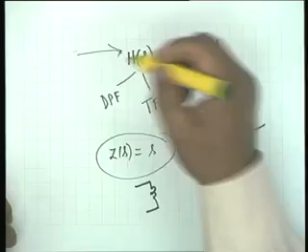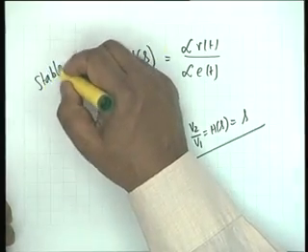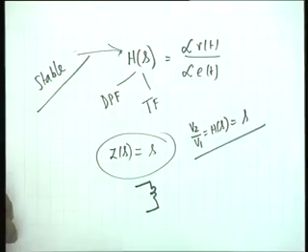It has a pole at infinity. Pole at infinity of an impedance function or admittance function is perfectly alright because we know how to realize it. But pole at infinity of a transfer function makes the transfer function unstable. That means as frequency increases, the output increases indefinitely. So the output is not bounded even if the input is bounded, which means that the function is unstable. So one of the criteria for a transfer function synthesis is that it must be stable.